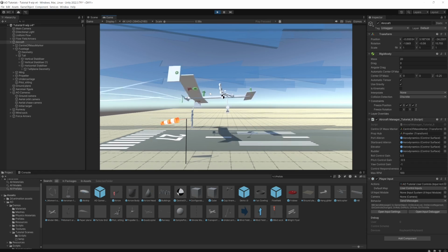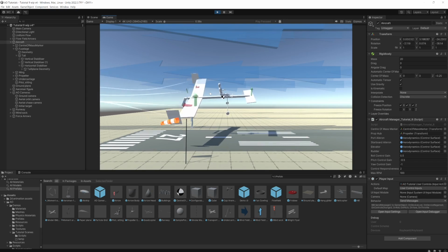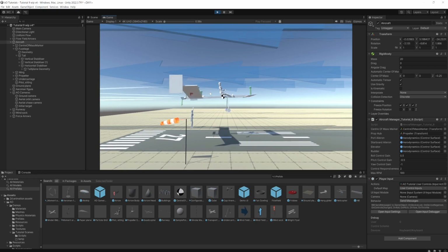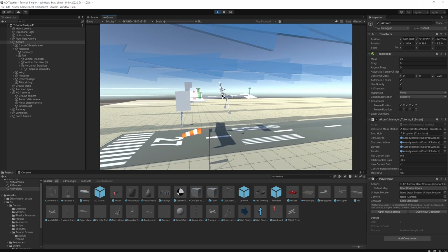So actually, without doing very much at all, we've got an aircraft that is obeying what it should do for a controllable and stable aircraft. Kick in some rudder, swings to side. Okay, so pretty happy with that. But one thing I do notice is that it's actually not very responsive. So I'm pulling full elevator on and it doesn't actually change very much.